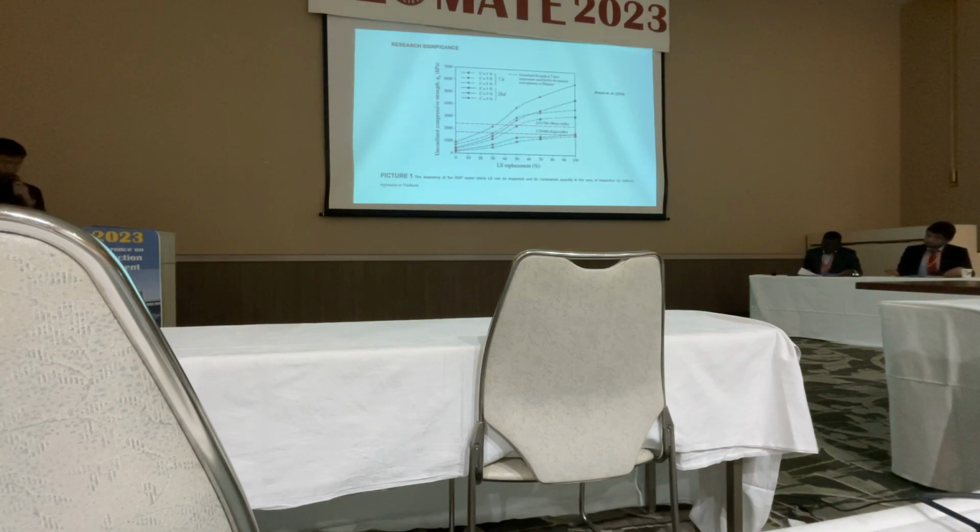From July 2019, a study used stabilized laterite soil as pavement material. From the standard of Thai highways, the minimum unconfined compressive strength for light traffic is 1,724 kPa. We can see that if we mix laterite soil with cement at 1% and cure for 7 or 8 days, the unconfined compressive strength can be used as base for light and heavy traffic.